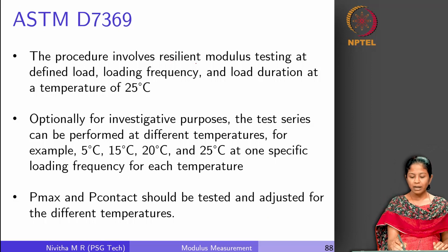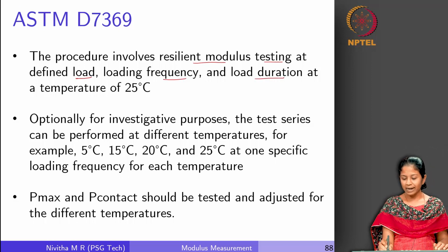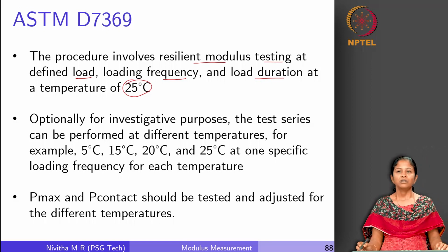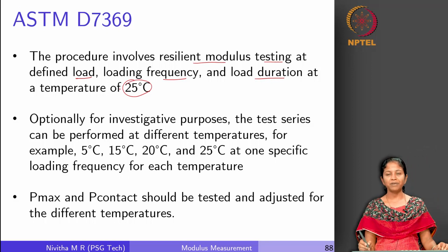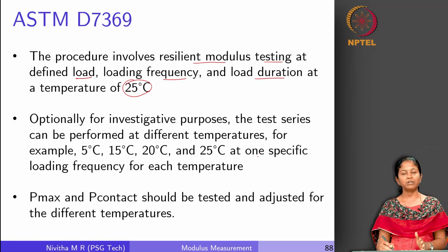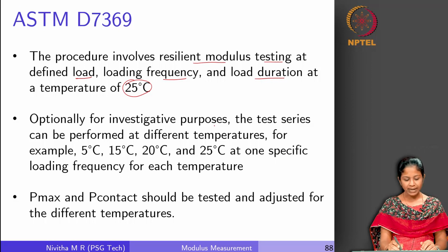This procedure involves resilient modulus testing for a defined load, for a defined loading frequency and load duration at a temperature of 25 degrees Celsius. So, as a standard, it is specified to measure the resilient modulus at 25 degrees Celsius, but as we said, if needed, we can do the same procedure for other test temperatures also. So, optionally for investigative purposes, it can be performed at other temperatures, and some indicative temperatures are 5, 15, 20, 25 and so on.